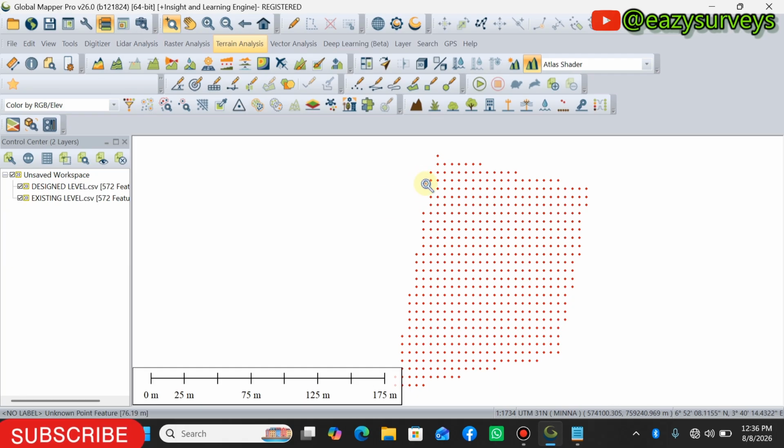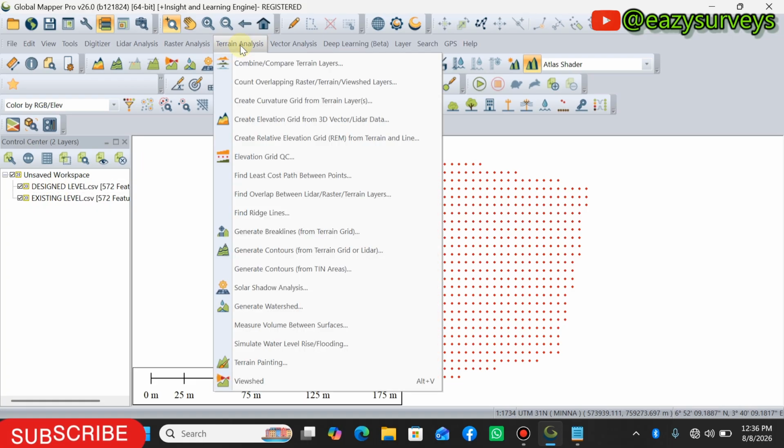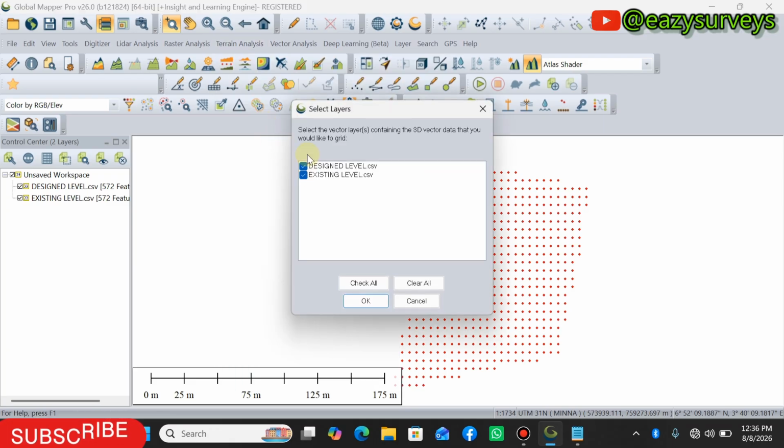Then the next step is to create an elevation grid from these two sets of data separately. To do that, you click on your terrain analysis here, then you scroll down to create elevation grid. So it's going to ask you which of the layers, so you need to uncheck one to leave one checked. I want to create for the designed level first.